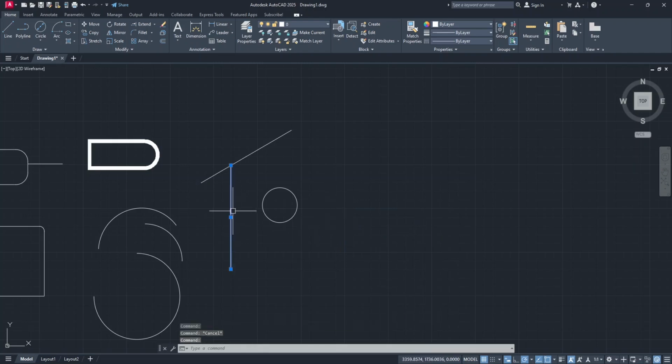Now select this line and this line. Select mirror, click on this line, point downwards, and make sure your polar tracking or auto mode is on. You are at 90 degrees or 270, and just click. It will ask you whether to erase the source object after you mirror it, or no to keep them both. I will select no to keep them both. And this isn't exactly at the middle.